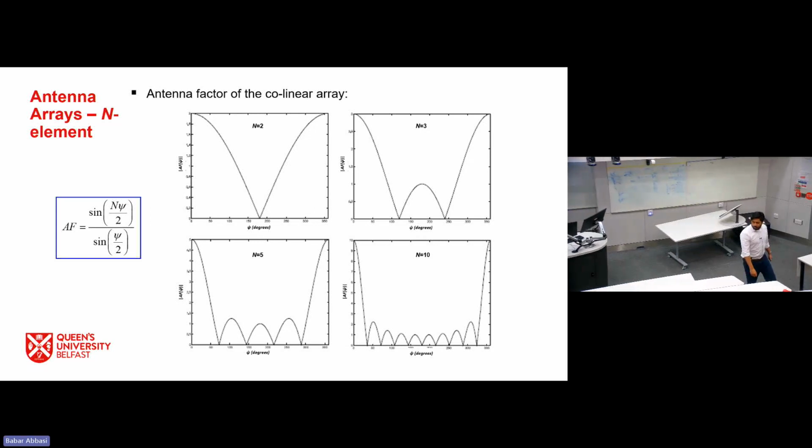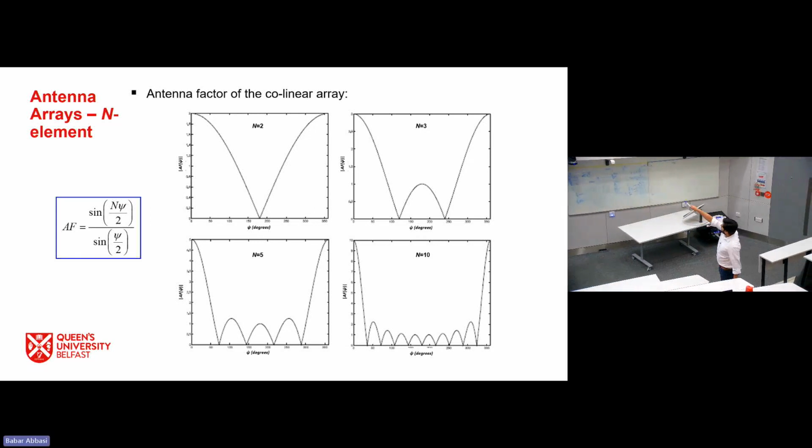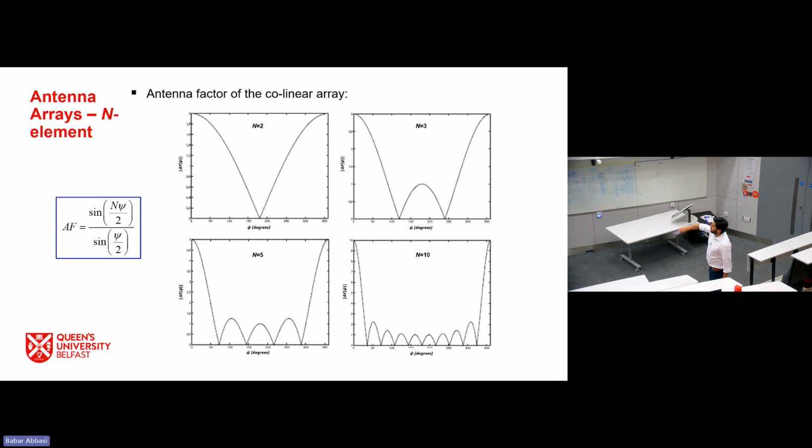Okay. So in this diagram, if our n is 2 in this array factor expression, then my resultant vector will look something like this. The resultant plot of this expression will look something like this. What it is telling us is the array factor is 2. It means it is increasing the energy by 2 times, but it has 1 null. That's good enough for me, no problem.